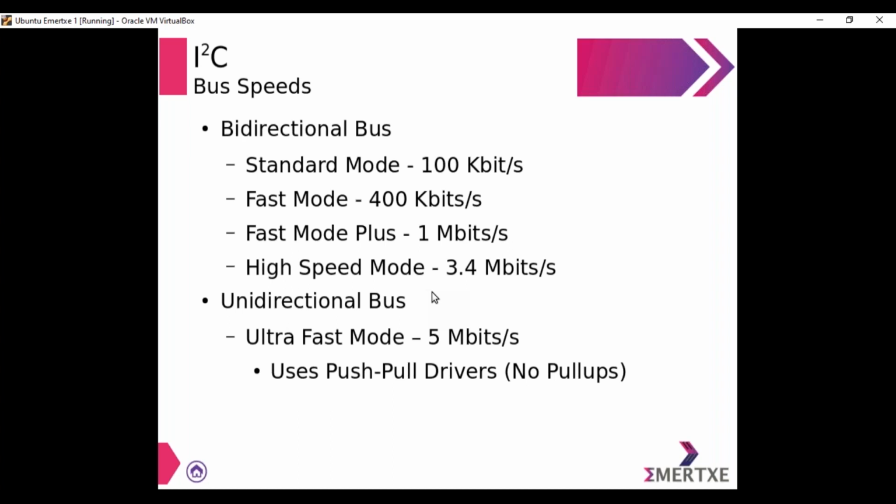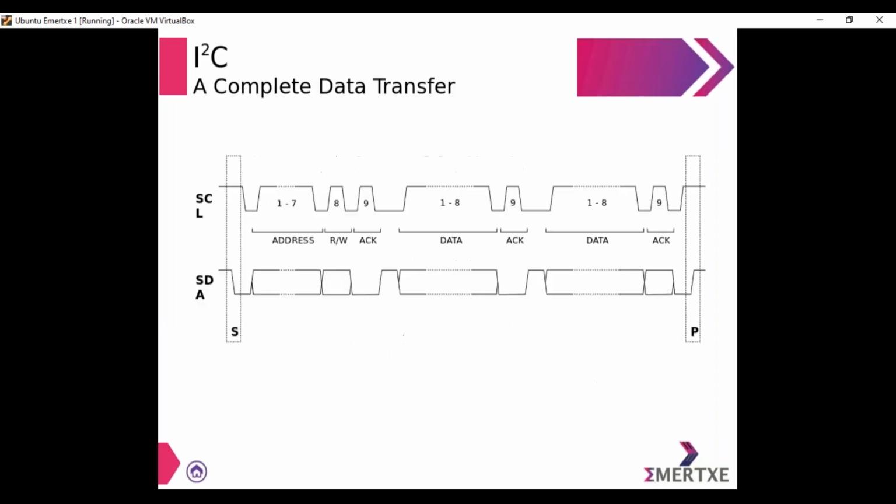Now, different microcontrollers support different modes. So, depending on the available mode, the configuration has to be made. And all of these make use of push-pull drivers, so no pull-ups are required. So, this is the bus speed and the different modes in which the bus is going to work. Any doubts?